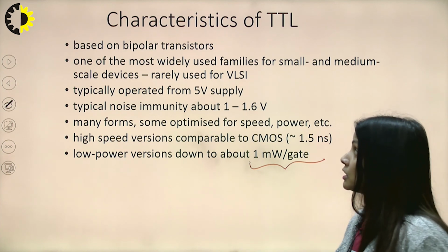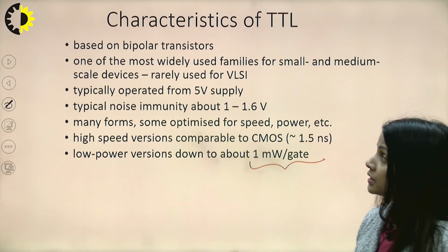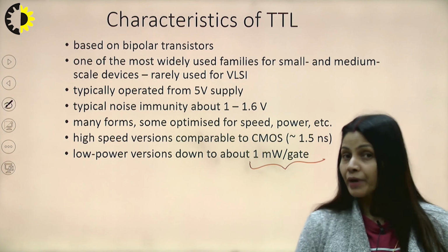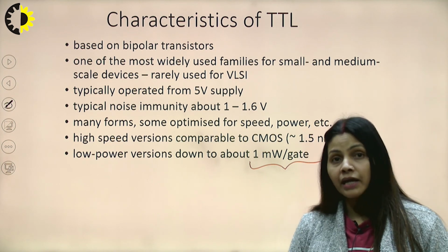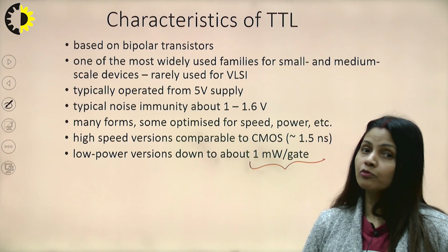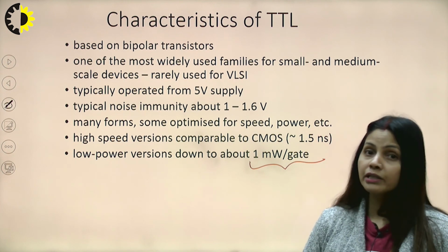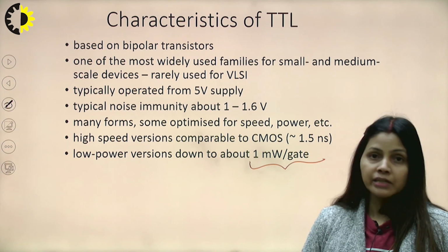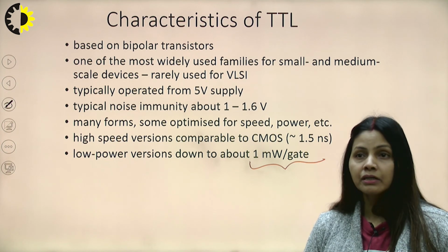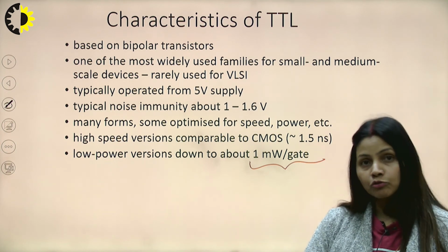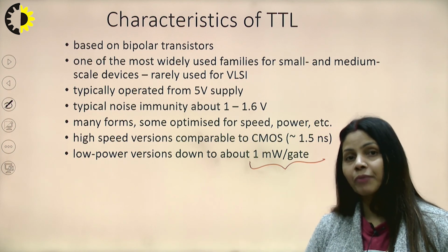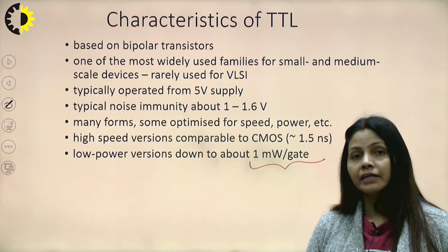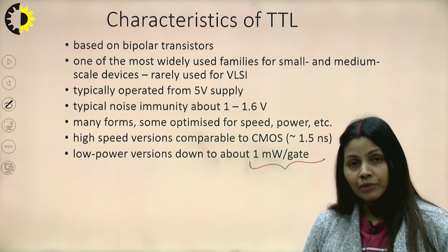So the TTL logic characteristics have also been discussed. One more thing we need to practice is numericals, which will be based on the input and output voltage ranges. But before that, you need to convert all the transistors into diode logic, and using that diode logic, you apply some network theorems: if the circuit is short, all the current will flow through the short circuit and no current will go to the resistive path. These are some small concepts. Apply them, find the condition of the transistors, and analyze the circuit completely, and hence the output.